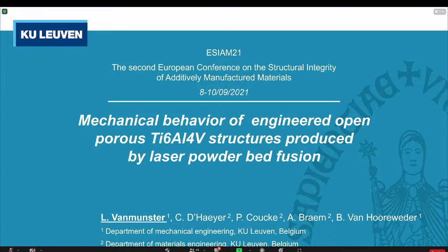Yeah, indeed. And also because we are talking about fracture mechanics a lot, did you also do fractography to see what's causing the failure of your material if it fails at some point? We didn't yet do it on the inclined fatigue test, as we will try to do it after the silica infusion, which I was talking about, since we think that there might be slight changes in the way it fails once the pore channels are filled with the mesoporous material. But at this point, there was no fractography done yet. No.